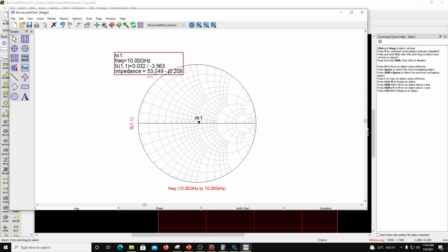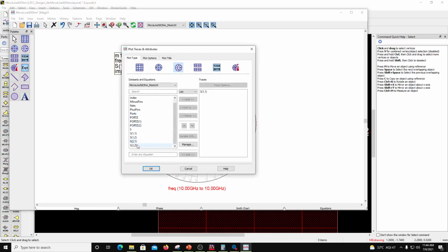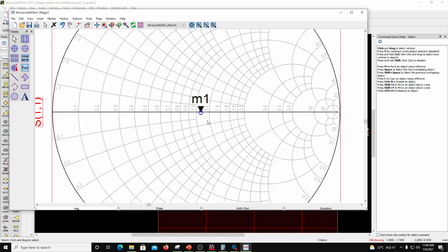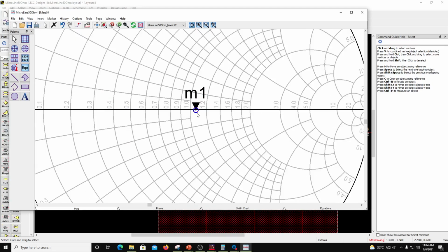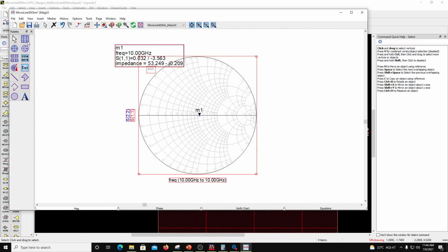So it is going to look at 53.2 ohms rather than 50 ohms. So it's 3.2 ohms extra. Okay, so similarly if I put S22, it is underneath that only, right? And let's look at whether it's a quarter wave.